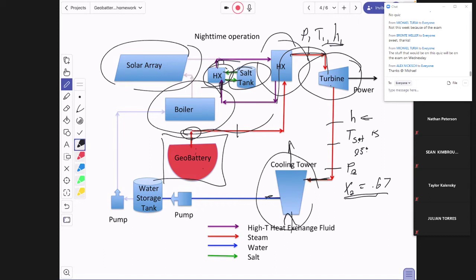And so now I'm taking air that is in at ambient air, and I'm actually adding water to it. So I'm getting like this evaporative cooling so I can get to an even lower temperature. So I want that pressure as low as possible. So as I go through here, I'm adding a little bit of water. I've got coming in here is cool air, and coming out here is completely saturated warm air. Okay, so again, that's just an example of it, just another heat exchanger and another summation of masses in, masses out, and summation of heat in equals heat out.